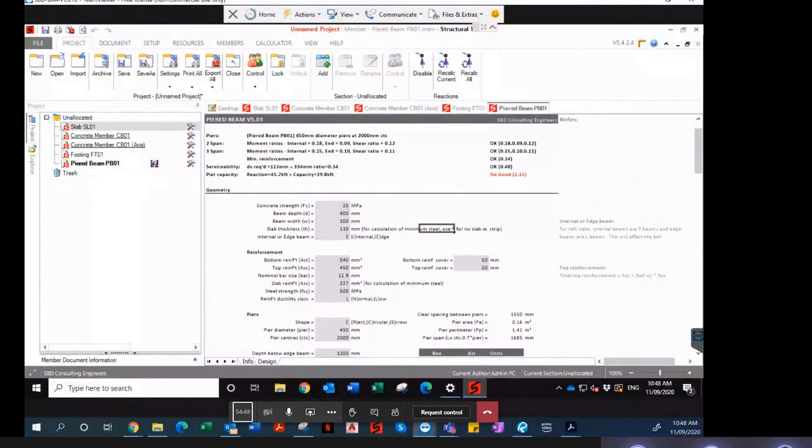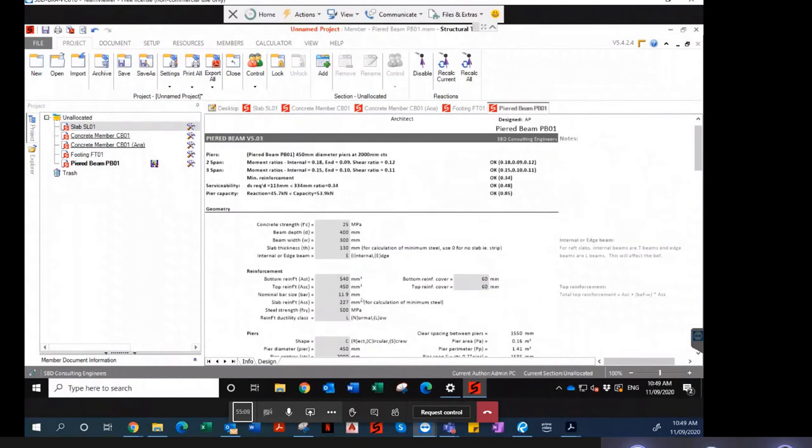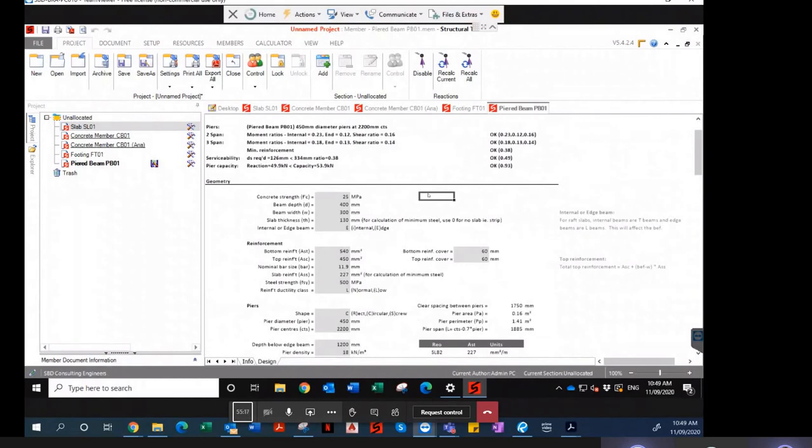So if we've got a 250 kPa soil in here, 250 kPa is not really good. It doesn't help us. We could go another 500. Say let's do 20 skin friction and 500 into it. Then it helps. We push spacings to 2200. So our critical thing when we're designing a slab system which is fully supported on bored piers is the bearing capacity of the piers.